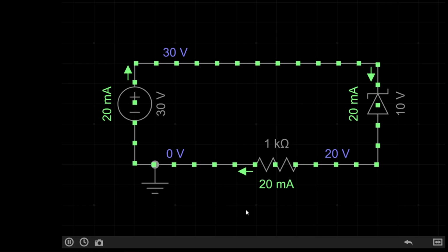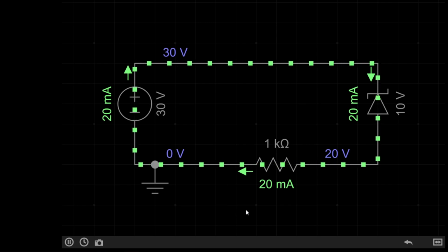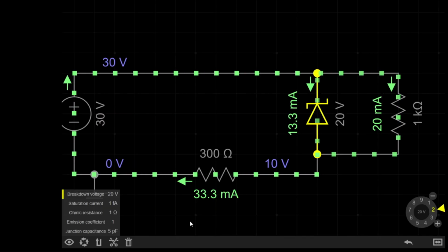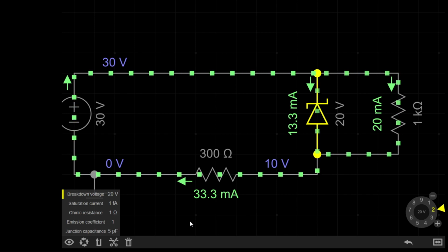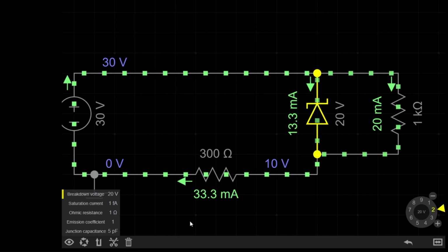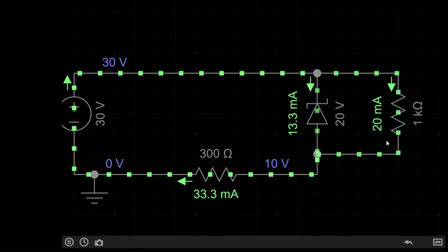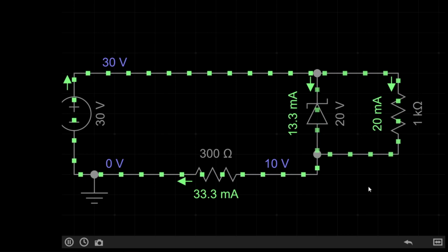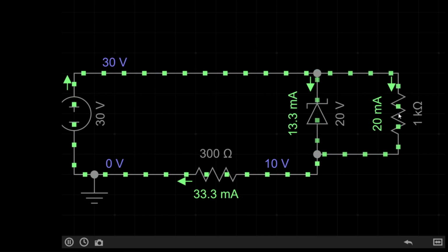Whilst this method works, it is considered to be not very sophisticated, as if the supply changes, then so will the voltage across the resistor. If instead we use a Zener diode with a Zener breakdown of 20 volts and connect our load in parallel, like so, we have effectively created a Zener diode voltage regulator, which maintains our load at 20 volts.